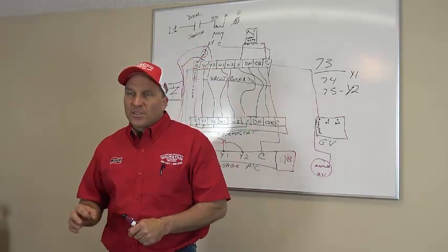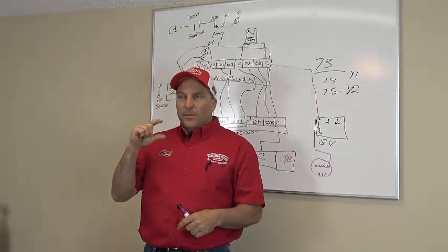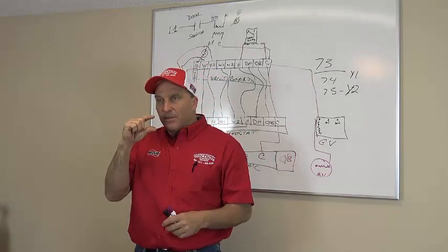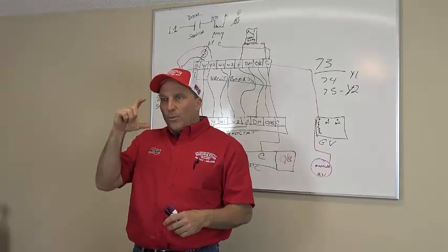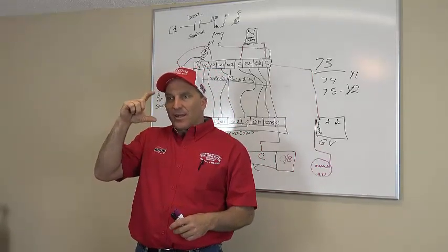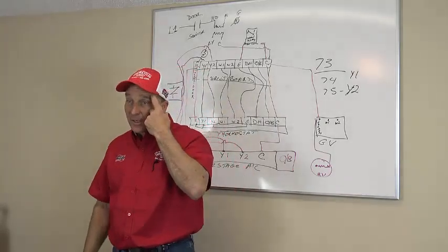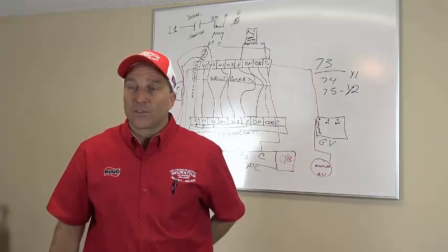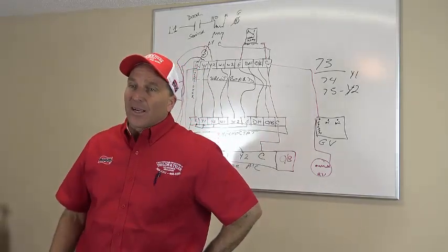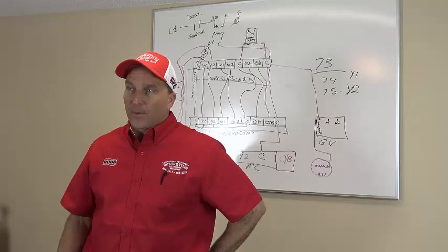So on the Rheem systems, there is a small C on the circuit board that tells you it's first stage. And then when you see the whole little printout comes out to a big C on it, that tells you it's second stage. Okay? You can't charge this system up and get your superheat and subcooling when it's on first stage. It has got to be on second stage to charge this system properly. Okay?